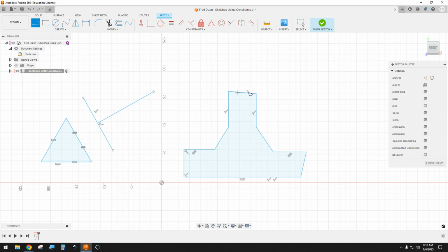So what we can do, we're going to constrain everything to be 90 degrees and equal. So let's do the 90 degrees first. So click here and click here. That's always going to be 90 degrees. This one will always be 90 degrees. Okay, it's 90 degrees already, perpendicular. Let's try this one. It's already constrained, so it's over constrained, which is fine. Now we just want to make sure that this is equal to this at all times, and this is also 90 degrees.